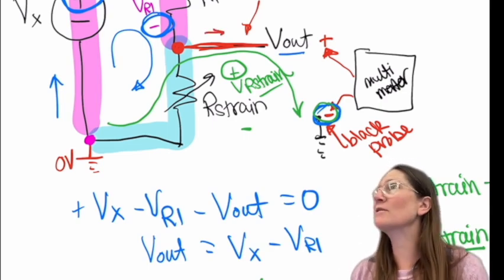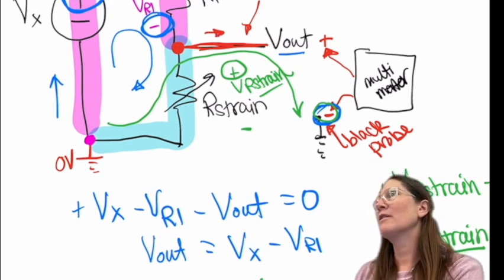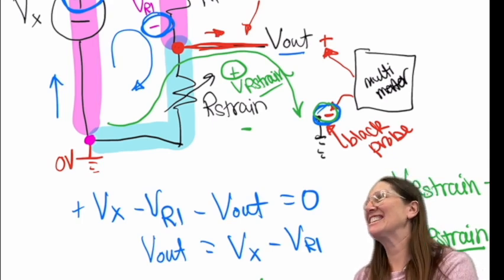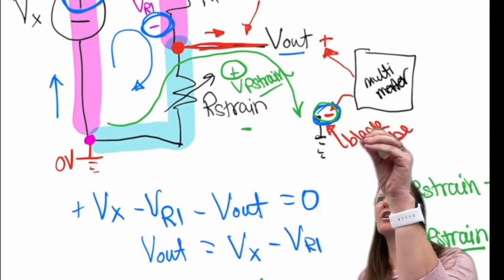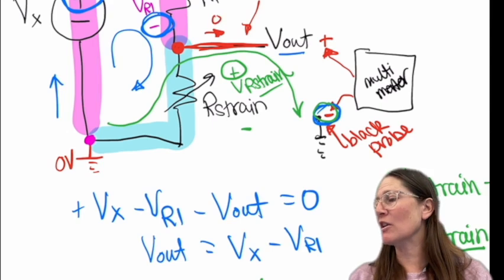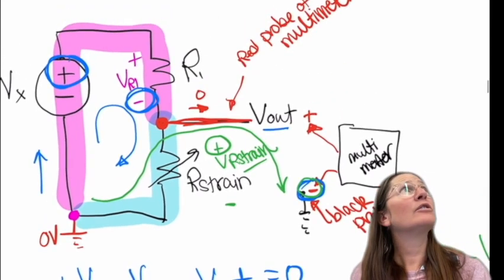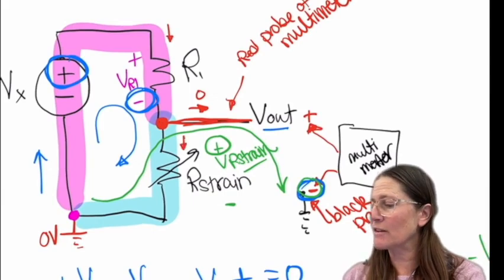Right here. Is there current here? I heard somebody say it. Is there current here? It's a floating wire, so there's not going to be any current there. So there's only one branch, so one current, and the same current is going to flow through here and here.